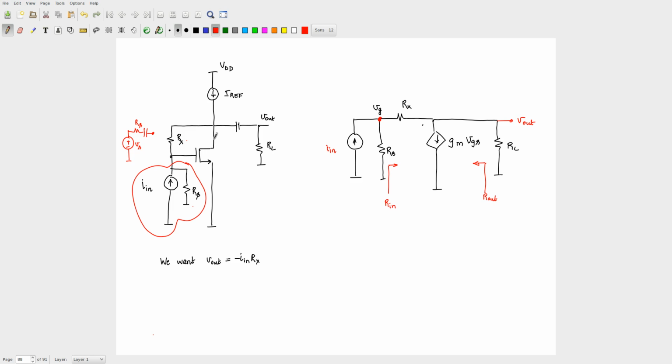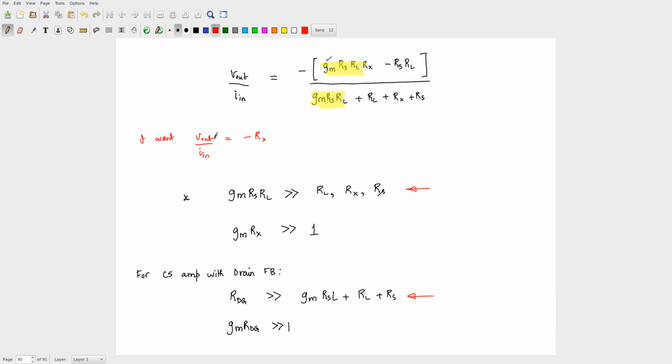On the other hand, if Rx was small, which is what we are getting now, you will get stronger feedback, and that will allow you to basically make the current controlled voltage source. Okay, and the magnitude of small and large and all of that are here, right? Because here you see Rx is less than something, so this is basically Rx being small.